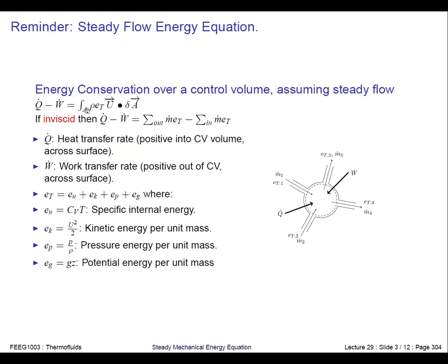So we are not going to make this inviscid assumption. We're going to work with this particular equation. Just to remind ourselves, we've got this total energy, and it's the sum of all those components: the three components that we had for the Bernoulli equation, kinetic, pressure and potential, and we've got thermal energy in there as well. We neglect thermal energy, but we do it in a clever way, and we will come to that in a minute.